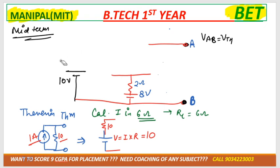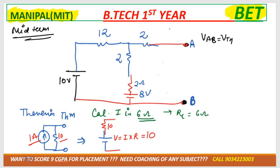So what can we make of it, a simple circuit. This would be 12 ohm because 10 and 2 are in series. This would be 2 ohm and this would be 2 ohm. Correct? Now 2 plus 2 is how much? 4. So I am combining this with a single resistance, that would be 4 ohm. Now we simplified the circuit, and now particularly for this circuit we can easily get the value for VAB. So now tell me if there is any doubt up to here.